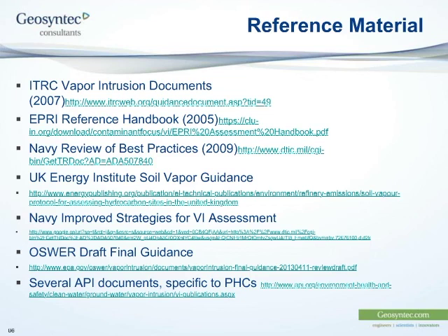So it'll depend largely on how much drawdown occurs. Now, some groundwater pump and treat systems are designed so that they aggressively lower the water table. That can happen, for example, where there's an LNAPL and you want to expose it to the gas phase because it can be remediated more rapidly through soil vapor extraction, for example. But if there's not also vapor extraction or bioventing going on, then it could actually increase the risk of vapor intrusion, and maybe even more so if it's chlorinated compounds.